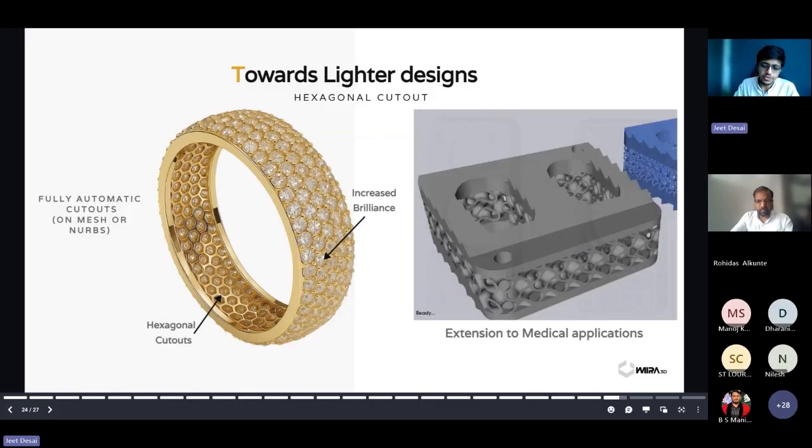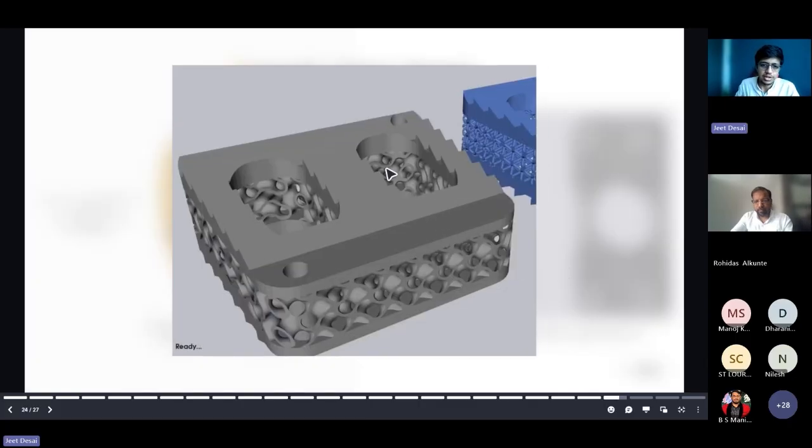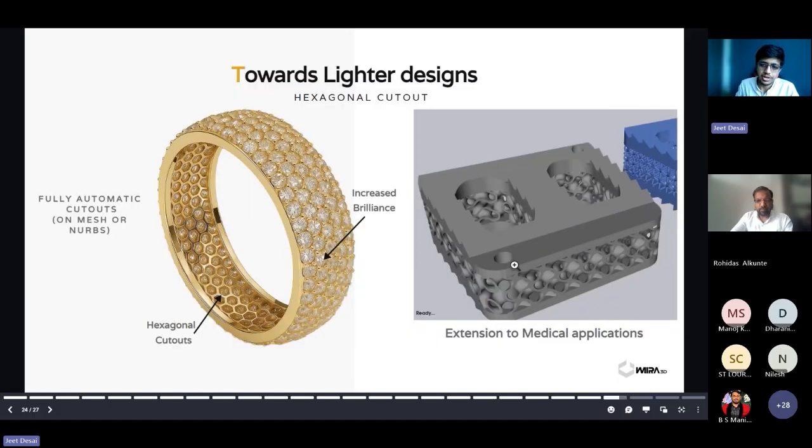Taking this idea of scooping further, we've made a solution for a spinal implant. This is normally solid, with no lattice inside, which makes it very heavy, and it's made via additive manufacturing. Here we've preserved a few surfaces, and for the rest, instead of a hexagonal lattice, we've added a gyroid lattice. We are able to add any kind of lattice, like rhomboidal, gyroid, or Schwartz lattice. Software plays a very important role. When we add lattice, this is not even possible on CAD software. CAD software cannot make gyroid lattices or rhomboid lattices. This is only possible by very specialized software.